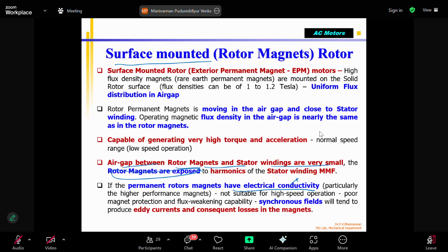We know that the torque produced is proportional to the rotor magnetic field and the stator magnetic field. So if the magnetic field is getting reduced, because of heat and continuous exposure, the permanent magnet will lose its magnetism, and then torque production drops. Initially, for example, we bought a surface mounted permanent magnet synchronous motor, say 50 kilowatts for your vehicle, with torque of say 150 or 200 Newton meter. For the first few days it is fine, but as time becomes longer.